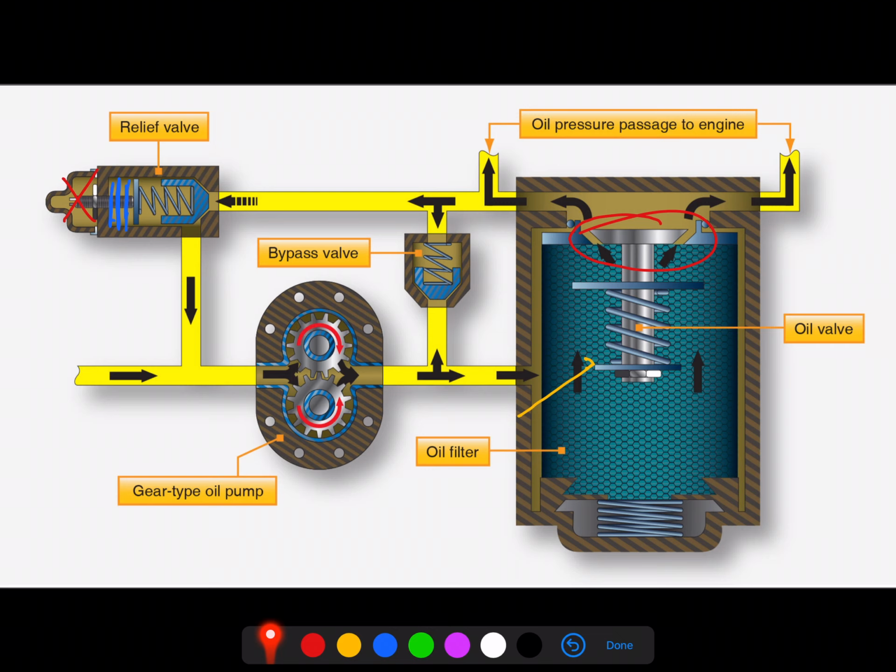This has something to do with what we call draw length. Namely, if we have a gap of air between our pump and wherever the source of that liquid is, in this case oil, if that length is too long for what the pump can draw through, we are not going to be able to draw a good head pressure of oil through the pump and supply steady oil pressure flow through the rest of the engine. So we can effectively wind up with a dry operation if we aren't careful to pre-oil the engine.